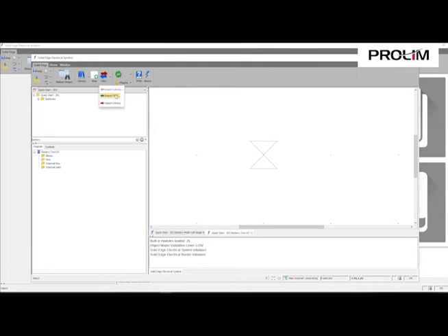So it literally just pulls all that line work, all that text of that DXF that you've created, and depending on what ECAD system you're using, you may have to convert that over to a DXF in order to pull that into this system. But you simply scale it and add any necessary elements to convert this dumb geometry into intelligent geometry. So once we set this geometry up here from, say, AutoCAD as a DXF, we can then go in and add all of the pins and all of the other electrical components that are going to allow us to do testing on these diagrams, to control the diagrams, and even simulate the connectivity of the design in the design environment for validation purposes.